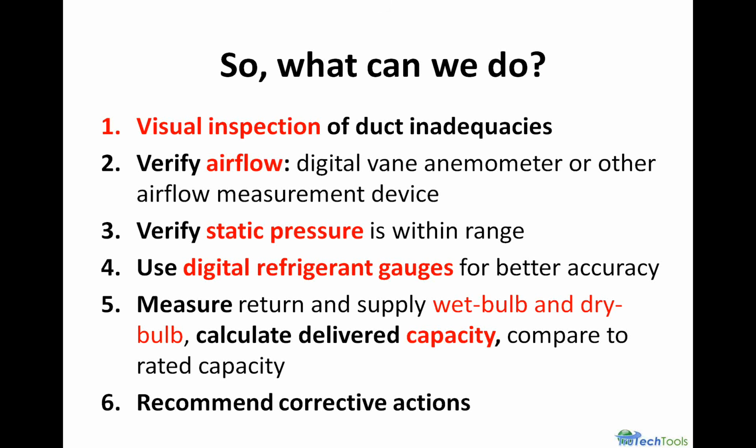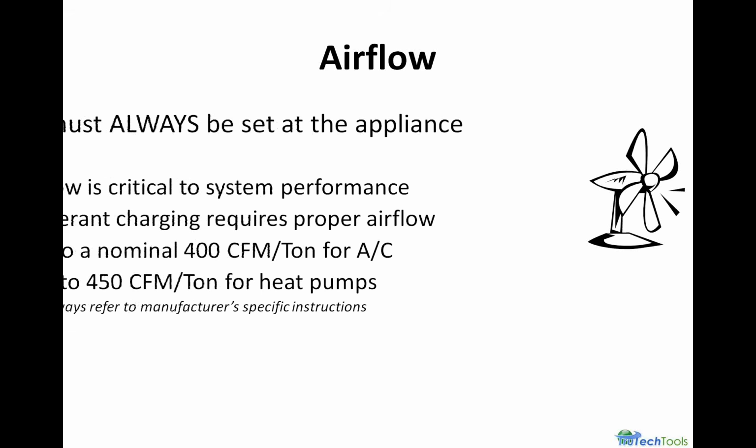We're going to use digital gauges for better accuracy. Then we're going to measure return and supply wet bulb and dry bulb and calculate delivered capacity compared to the rated. And then if we have to, we'll recommend any corrective actions.